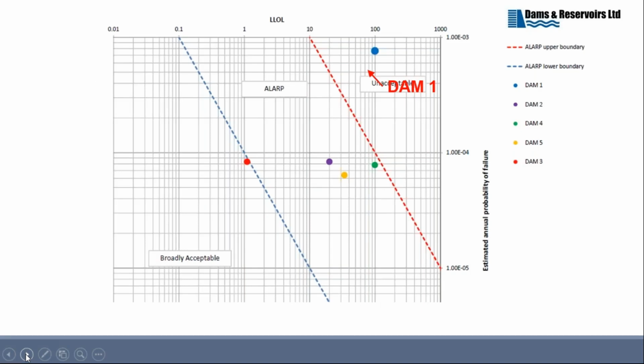So in very simple terms, when you do a portfolio risk assessment, take this slide here, I'm showing 5 dams with different types of failure modes: internal erosion, some sort of piping failure, instability, slope stability issues, and then some sort of foundation failure, leading to a summation to give us a total probability of failure. And you might have various other failure modes associated with that. But from my experience, the most likely and the highest element within that total probability is associated with leakage, with seepage, with internal erosion processes.